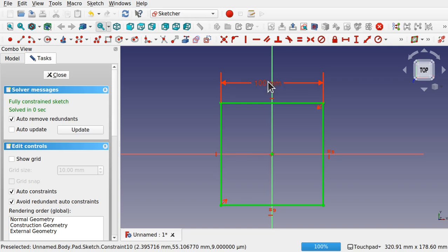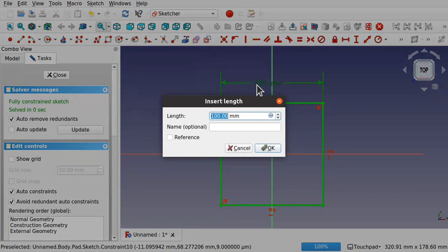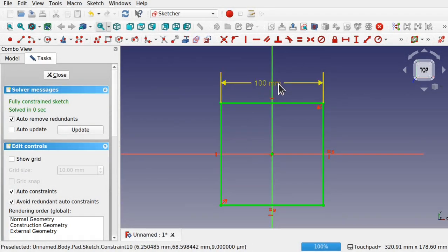Now the way to do that is to double click it, and we've got this name option here. So I'm going to name this SideLength. Notice that the casing will matter. So if I did lowercase side length, then they will actually be different constraints. Casing does matter in here. So uppercase S, uppercase L on those, and hit OK. So I've named this now.